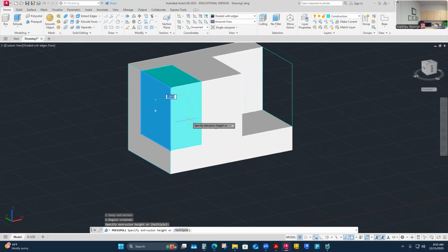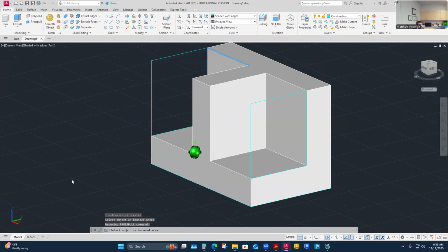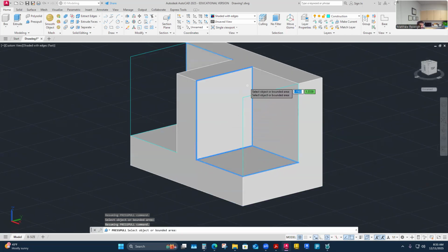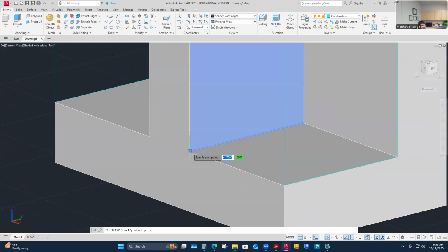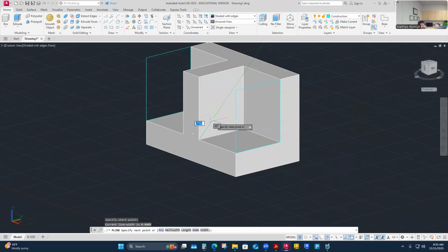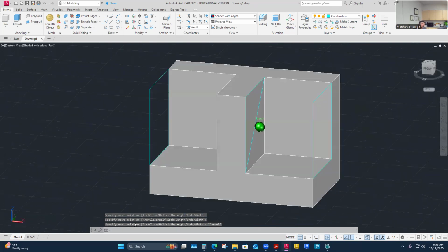Then it's a solid, adding a solid. Bam. So that's at least my L shape. And then I'm just going to do another sketch on this surface now that I've created. I'm going to do a polyline sketch here that's triangular. I kind of have all the points. I really don't need any. So the way I see this is I'll just go back in. I'm still on my construction layer with a polyline. And I'm just going to lock in here. I could do endpoints. I think this is a nice 3D endpoint, that blue square. I'm going to draw across here to here and back to this point and then back to this here. And I'll escape. So now I have another shape to press pull across here.